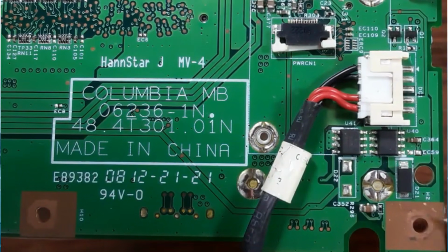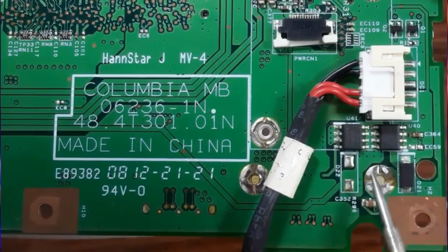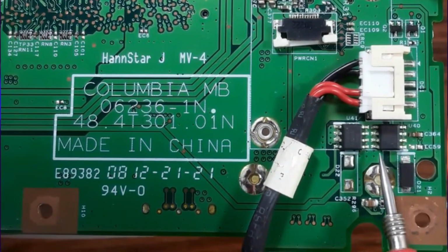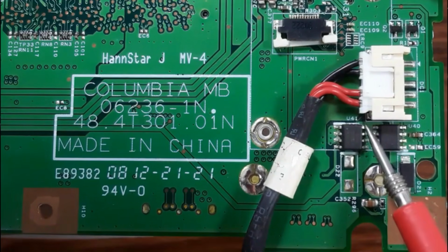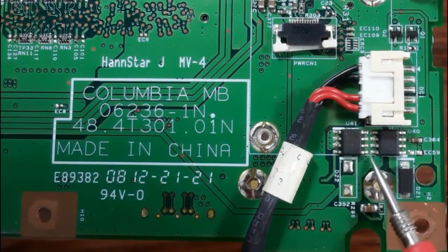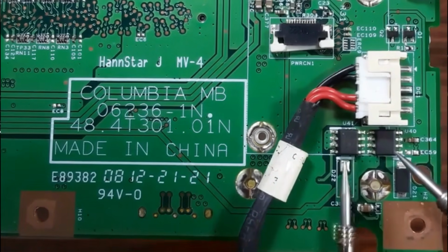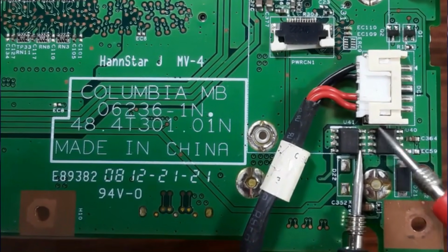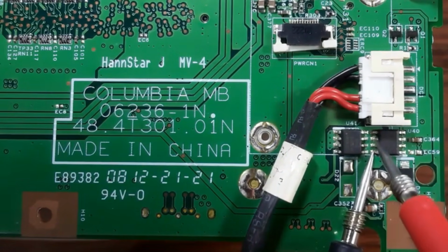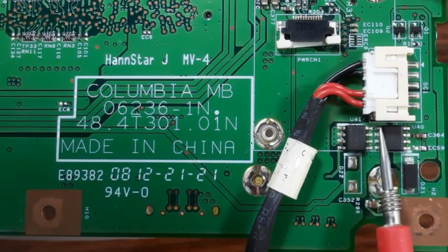Then this diode here is connected, as you can see, to the ground. Then here, if you focus here, as you see, we have the drain. This is the drain because all these 4 pins are connected together, and also here we have the drain because these 4 pins are connected together. So let's check these pins. So let's check this. Okay, so we have the second, the third, the fourth. Also these pins, the second, the third, the fourth.